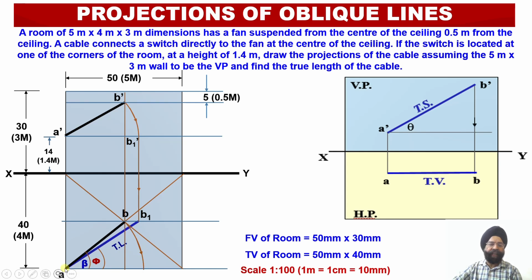So our needle point will be point A, open compass AB, and then through B draw an arc up to the locus line corresponding to the point A, such that AB2, because this is the second rotation, so the numbering of this point will be B2. So AB2 is the apparent length projection of the line in the plan. So this happens to be parallel to the vertical plane.